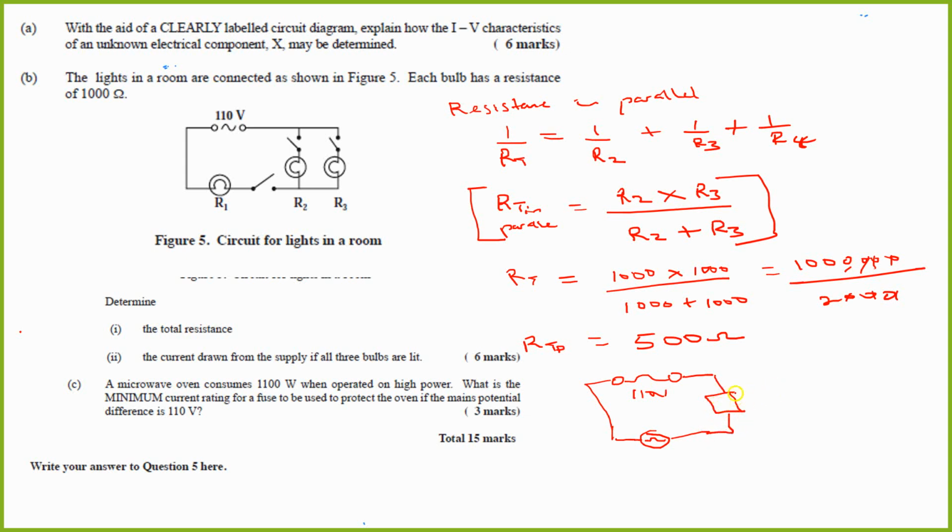And this resistor that we are drawing here is going to have the resistance of the two resistors that were in parallel. So this now is 500 ohms, because we would have found the total resistance using the formula just now. So I would just include that resistor back in this circuit, and I would already have R1, where R1 is 1,000. Follow me so far?